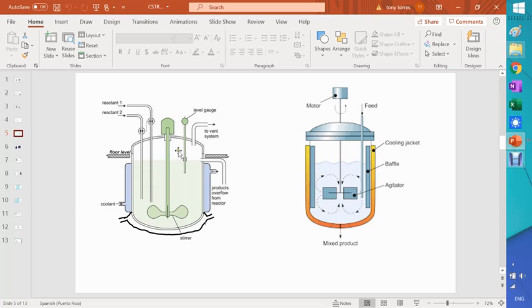More into it, for example, you can have vessels that have what I call a split jacket, one jacket at the cylindrical portion and a secondary jacket at the dish part, or you can have a full jacket like showing here in this reactor.